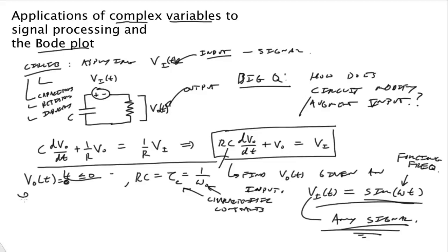All right, and then of course we take the Laplace transform of this system. So RC V prime plus V is equal to, Laplace transform to the other side, V in. This is pretty straightforward to do. That becomes RC times s, our Laplace transform variable.